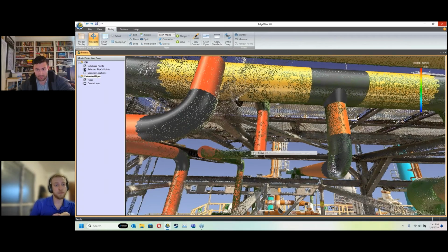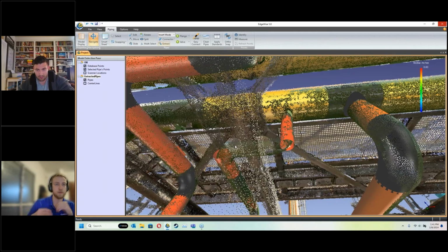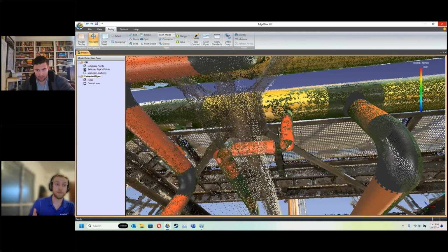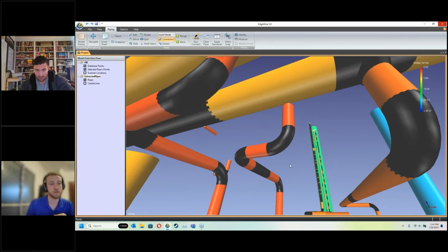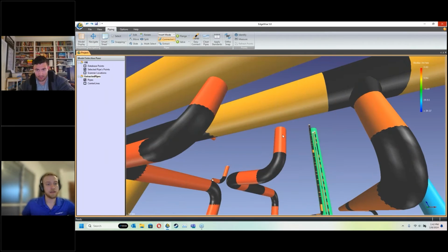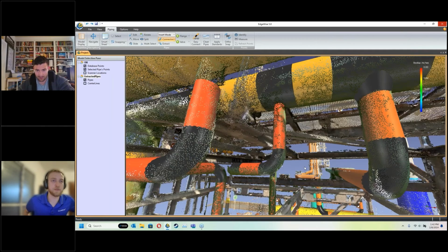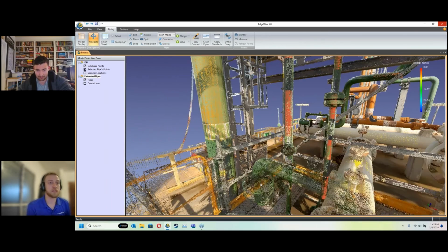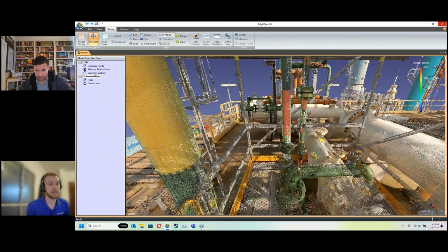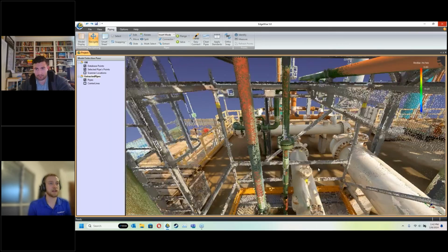If you unify your point cloud, if you're in any workflow and you decimate it heavily, that's going to really affect the performance for EdgeWise. So you generally want to maintain the default scanning that you're doing. If you do a heavy decimation and then give it to EdgeWise, it's going to perform worse than if you maintain that density and don't decimate it and give it that original data set.